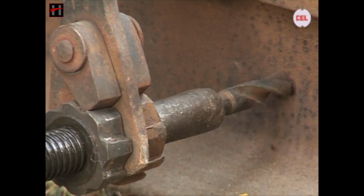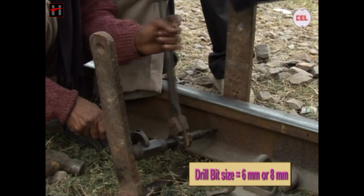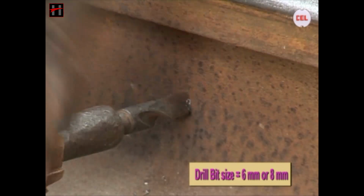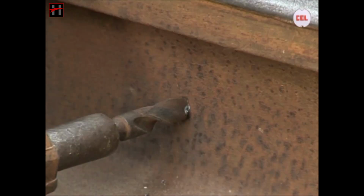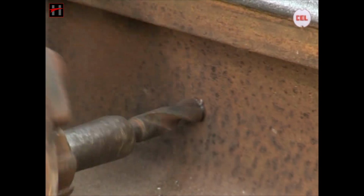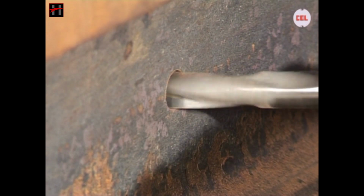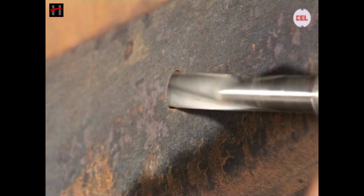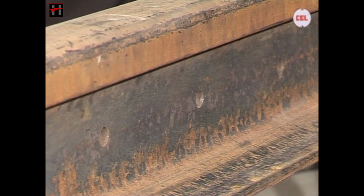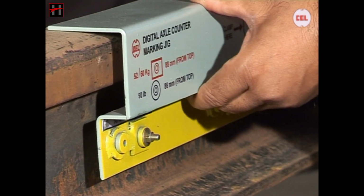Use a ratchet or drilling machine for drilling the hole. First, for drilling the hole, use a drill bit of size 6 mm or 8 mm. Then use a drill bit of 14 mm size for drilling the web as required. Drilling is done manually, but it can also be done using an electric drill machine like this. Verify the position of holes by fixing the marking jig with the clamp properly.